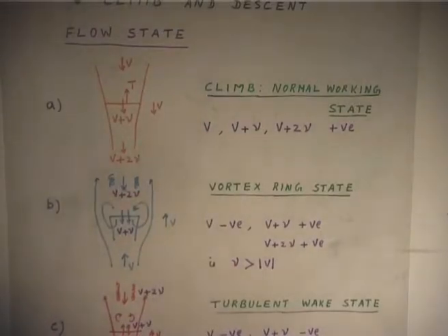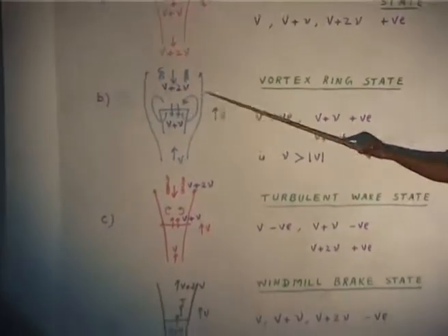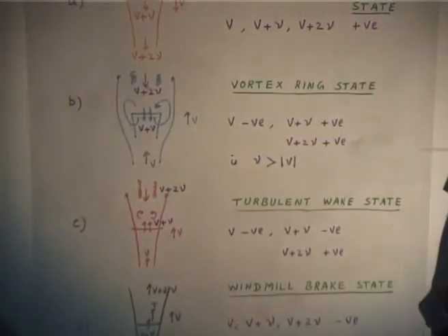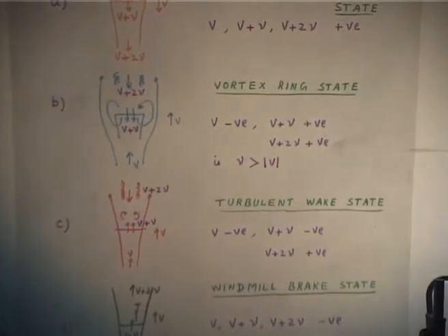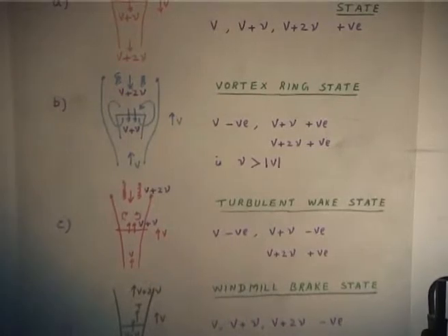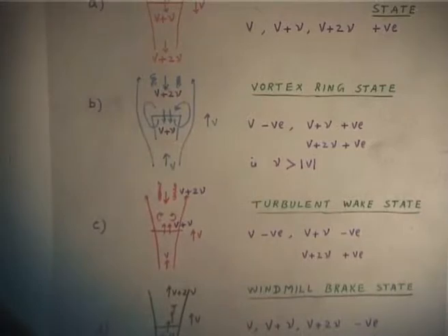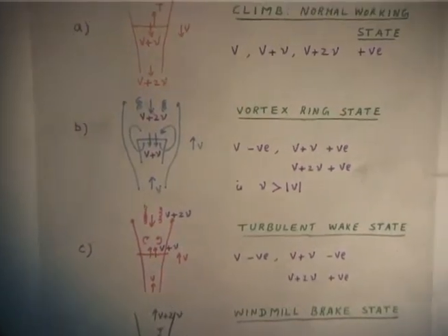What we say is, first it is hovering, it has just started descending. That means I have reversed everything. The flow V, if you are sitting on the rotor disc, far field down, actually down means that is upstream, velocity is coming towards you because you are moving down. So, it is equivalent to velocity coming, but then at the rotor disc, because the rotor is still supporting the weight of the helicopter, which is equal to T, for it to support, it has to push the air down.